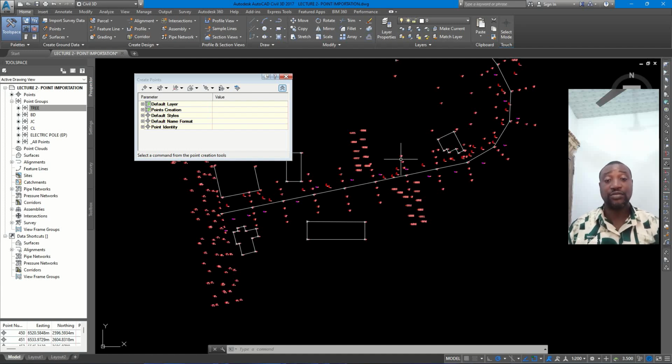We'll be relating all the buildings and all the junctions, and as well decide the alignment of the road and create the alignment style. And we will now start to see how we offset an alignment, how we can create a bay, a stopping bay along the road.